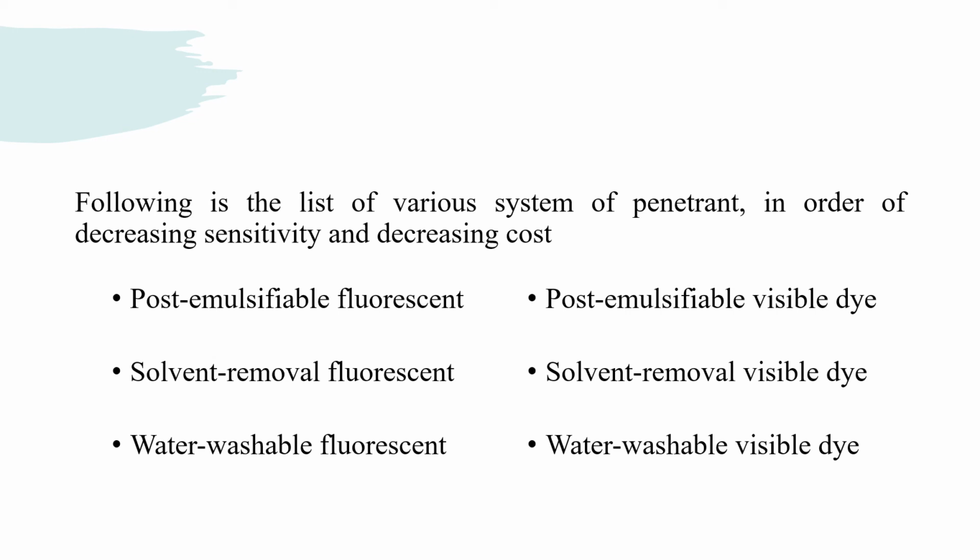So for the visible dye, the crack width is approximately 5 micrometer, and for the fluorescent, 1 to 2 micrometer.